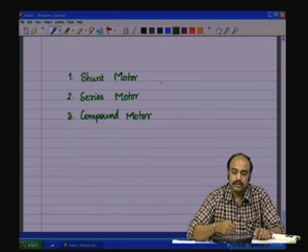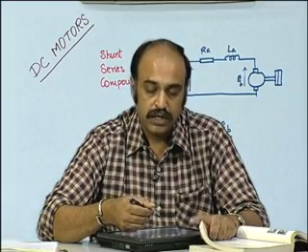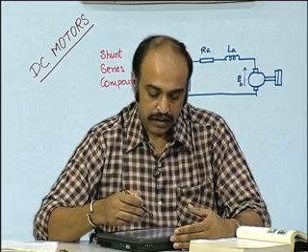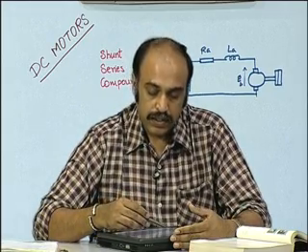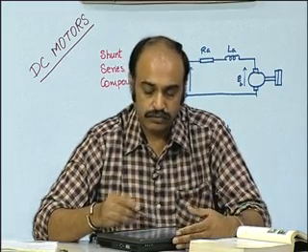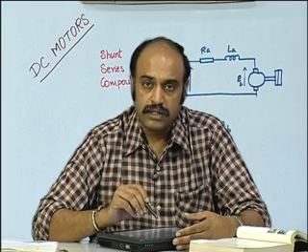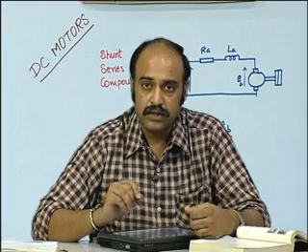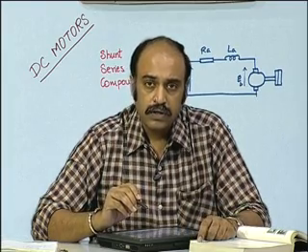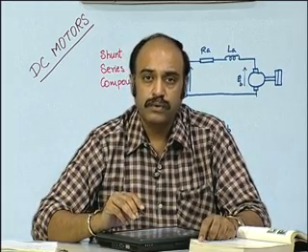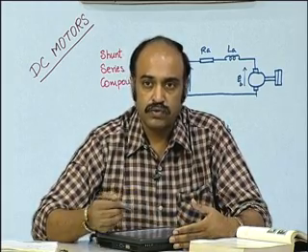Each has its own unique torque speed characteristics, which are useful for certain applications, and thereby we try to use a particular type of motor for a particular type of application, because the torque speed curve gives an idea of whether that particular motor can handle the load. The generated torque speed curve and the load torque speed curve will give you an idea of which type of motor can be used for a given application.